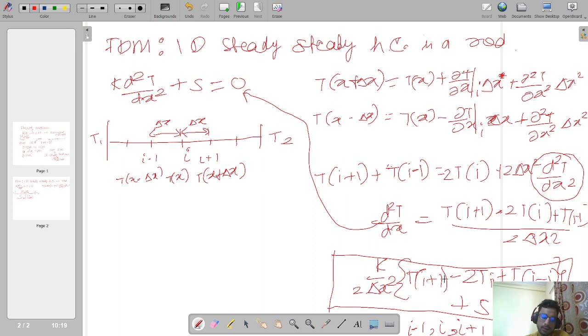Now if we apply this final discretized equation to the whole domain, it gives us the relationship between the points throughout the domain. This is how we solve the equation and get the correct results, if we establish the correct relationship between the neighboring points. That's how the iterative method works. So this is the final equation, and now we'll use it to write the algorithm and code in MATLAB to solve the 1D steady state heat equation using a numerical method.